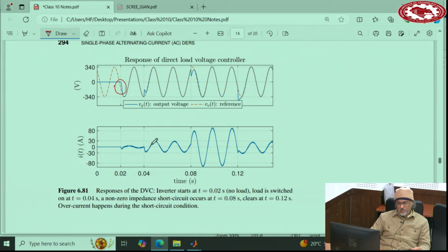And the converter increases the current. But the voltage does not really change. The objective is to control the voltage. At this point, a huge load, or you can say a short circuit, or something of that sort happens at the output. So the converter increases the current to keep the voltage at that level. So this is the behavior that in the DC part also I went through as an intermediary thing to say this is not a nice approach to do.